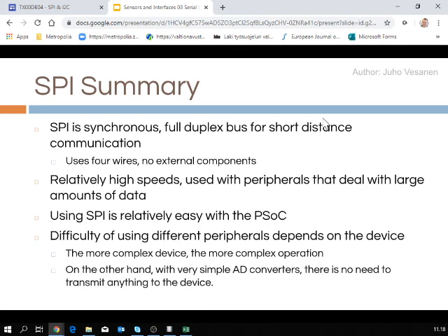Since it's synchronous and not that critical about timing, of course you can run one digital output as a clock with software, write another as a MOSI, have one signal input and read it as a MISO, and have one output as a chip select. So you can do a full software SPI, that's quite straightforward actually.